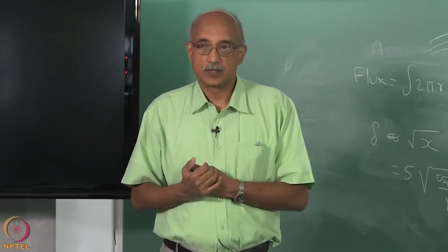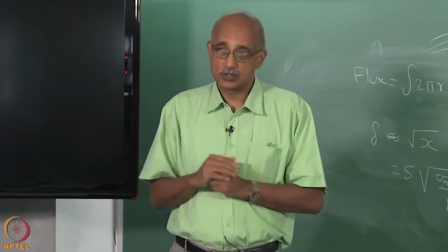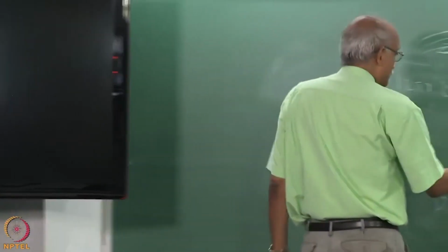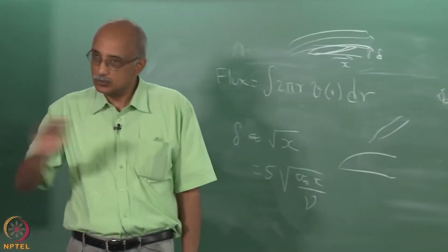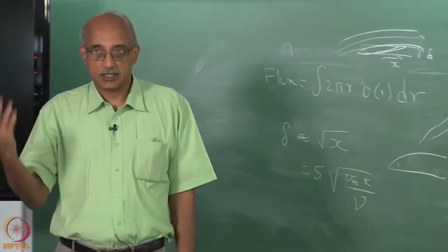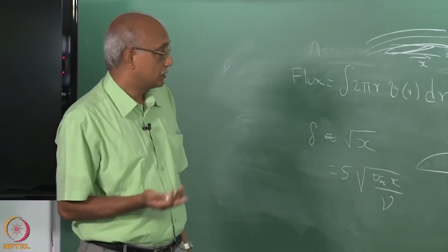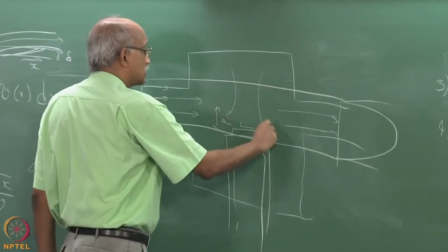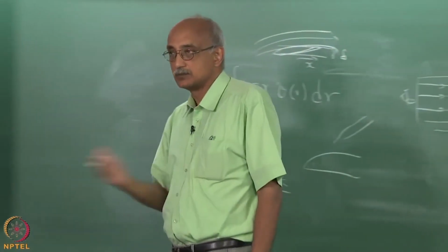So, how do you address that? I think the suggestion that was given last time was to tilt at an angle. That solution would still work in this case also. So, by tilting the plate at an angle, you can essentially force the boundary layer thickness to be much more uniform across the length of the boundary layer. Of course, there are other solutions such as again rotating the substrate and so on. Other approaches would include not flowing it in a horizontal direction, but as I mentioned in the earlier class, perhaps flowing it in a vertical condition to achieve stagnation flow.